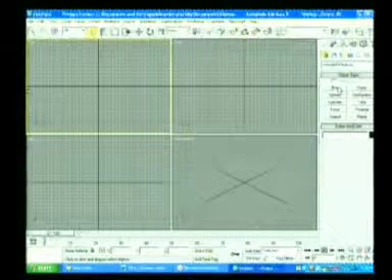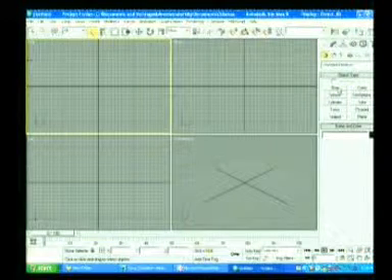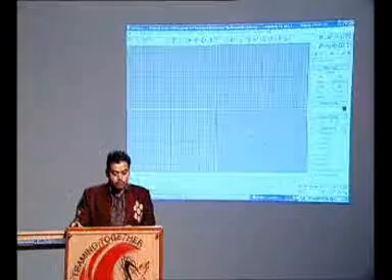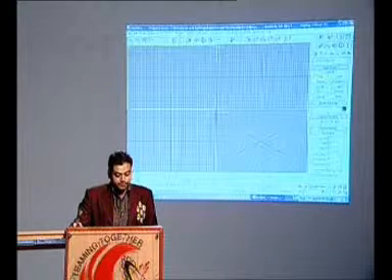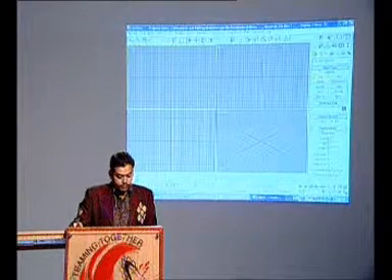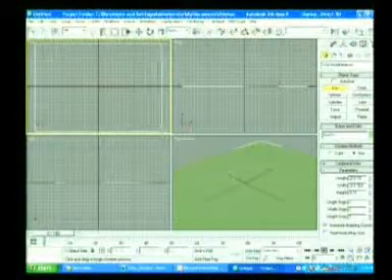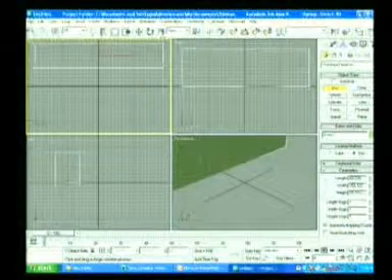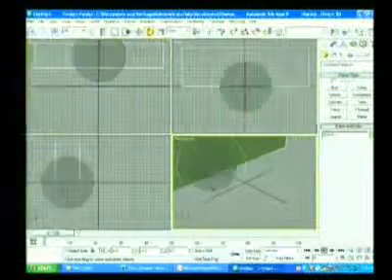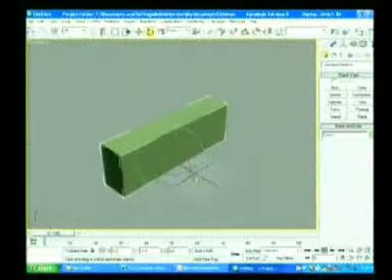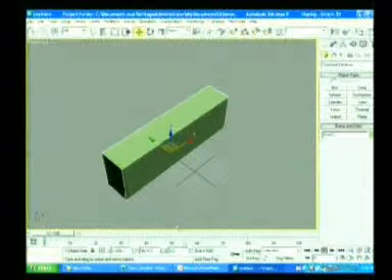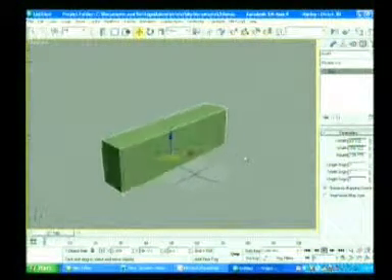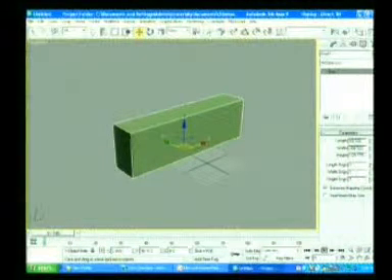In poly modeling, you will extract the faces from one model. Simply, if I want to make a table or a sofa in extrude modeling or poly modeling, then start with the front or top view, make a box, adjust the height, go to the modify list, and here we have segment division.